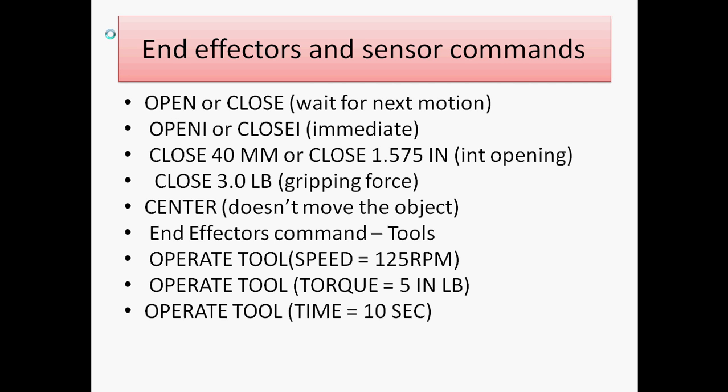Close 40 mm. So only the gripper should be closed up to 40 mm. So we are providing a limiting value over here. Then close 1.575 inch. So it is a value in inches. So that is the opening value for the gripper. So that's why we are writing close 1.575 inch.